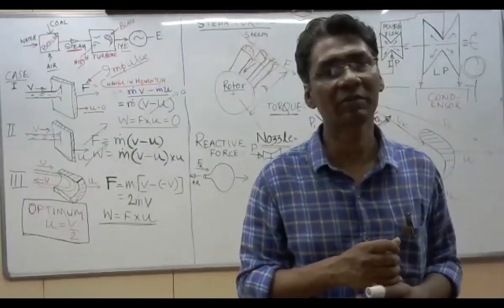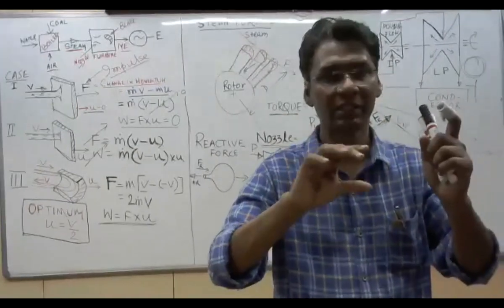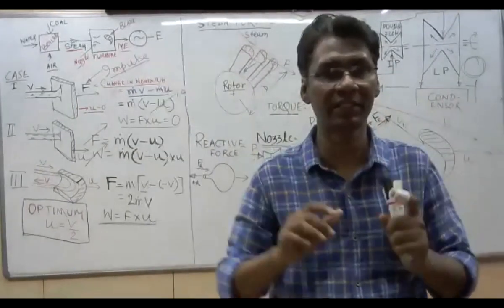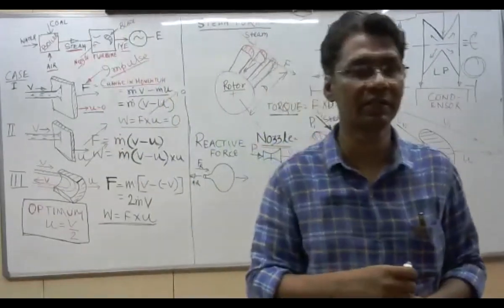The blades are almost the same size, because there is not much difference of pressure. That means in high pressure, similar size, with a little bit of change in blade size. In low pressure, the volume is higher, so there are bigger changes in blade size.